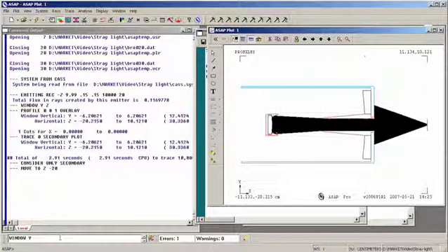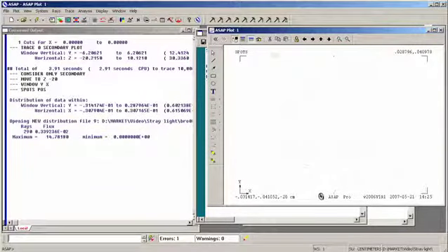We then set up a window and do a spot diagram. This is our spot diagram for the calculation, and we see that the size of this window, looking down here, goes from minus 0.03 to about plus 0.03. That's the size of our image. That's the size of the important edge that we're going to use to actually direct scatter towards the image of the detector in the secondary mirror.